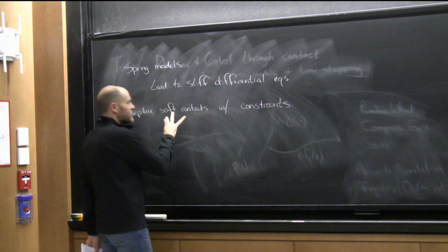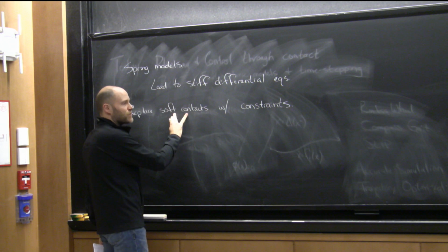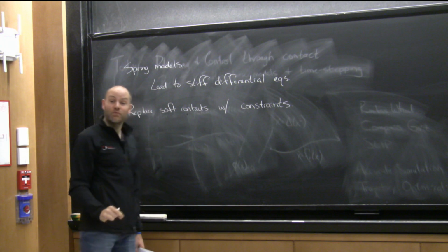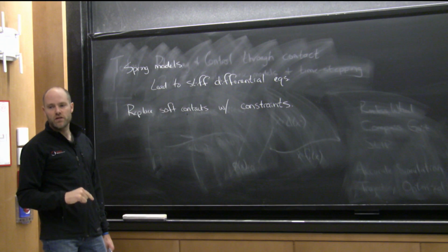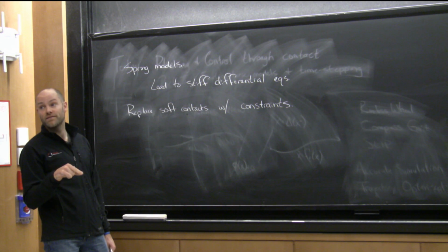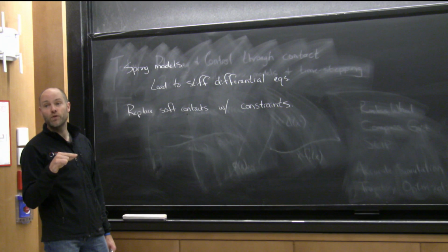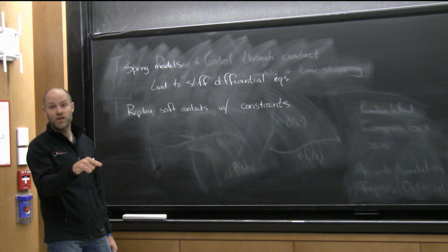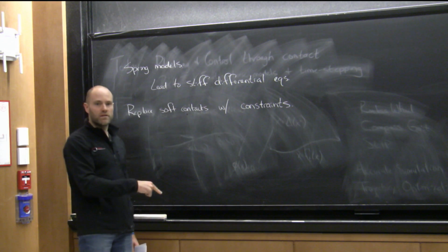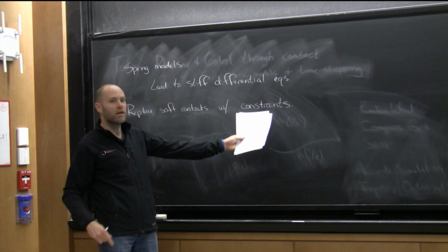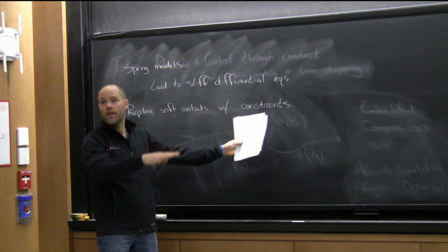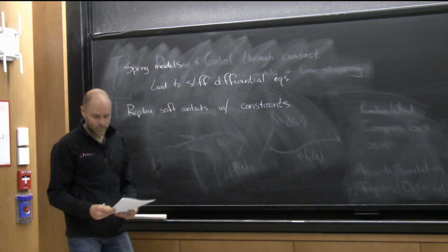You can think of this as a constraint, but a penalty constraint, and we can turn that into a strict constraint. And if we handle it well, then we can get some of the numerical benefits. If you could tell your solver that this constraint is active right now, then the solver has the opportunity to think about a constrained solution along that. Your trajectory optimization has an opportunity to think about that. Your feedback control has an opportunity to think about that. If you can tell it this is the constraint, it'll be satisfied over the next time, dt, then that becomes a numerically better thing to do.